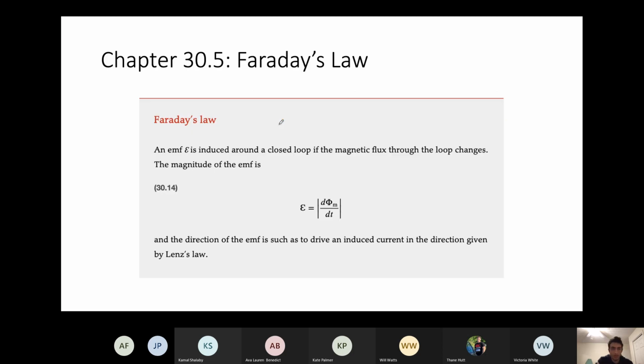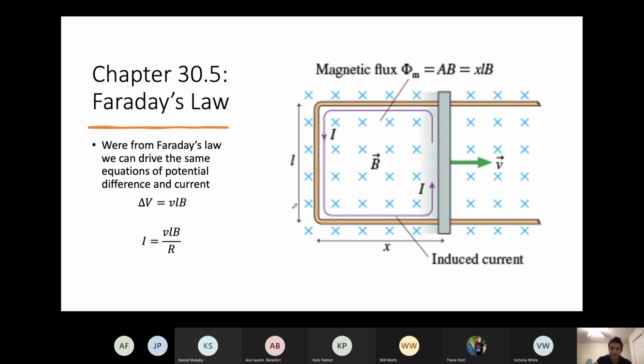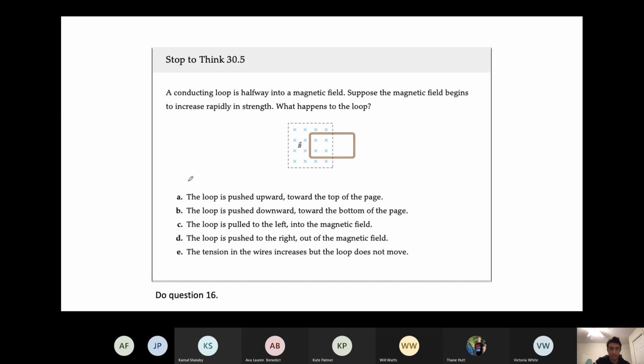I'm going much over the time, so I'll just skim through these. Okay, Faraday's law, just simply saying the change of flux over time is the potential, the EMF. So you can just look at it as delta V. Any change in the magnetic flux divided by the time will be your potential difference. That's simply what it is. And using this fact, with playing a little bit with the equations, you will get the exact same results we got before. Just simply what it is saying.